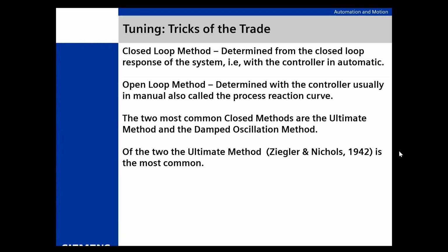Also, this may sound elementary, but you need to know with any controller how to abort. You need to know how to stop what you're doing immediately, because I may put a P, I and D in there that's way off. I put that controller back in automatic and it starts to go do crazy things. I need to stop it before it screws the process up or hurts somebody. So just make sure you know how to abort.